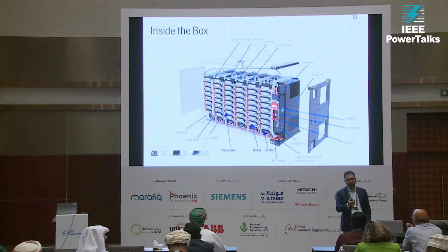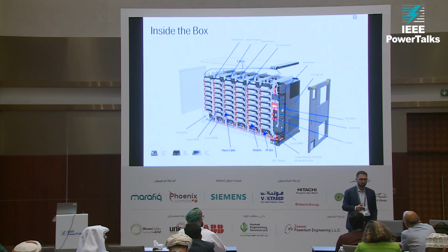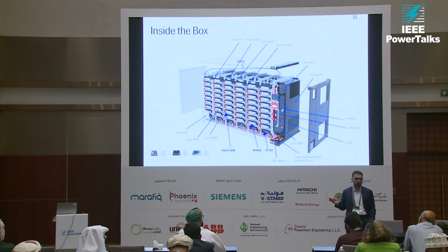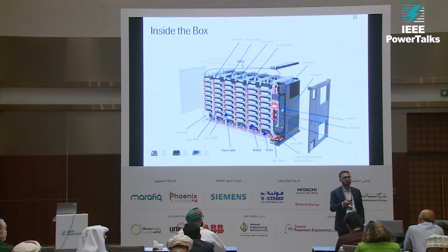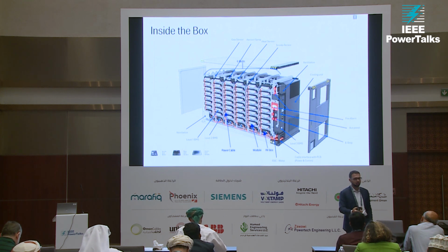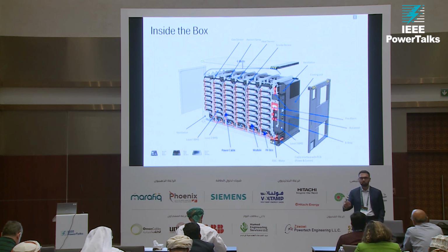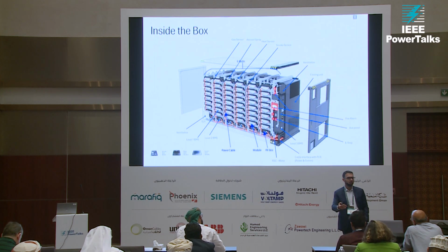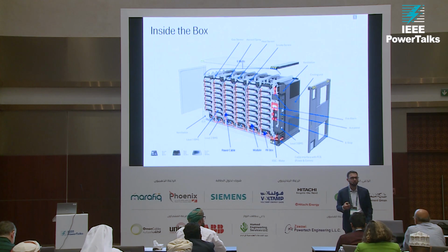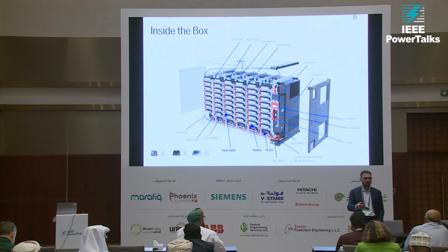Yeah, so that's a good question. That's a classification question, not really a device question. Just to speak on devices, we do have hydrogen sensors. So we do have measurements. The industry and the codes have improved to require a mitigation method that includes ventilation, for example. The original projects did not have that. So we did improve to actually include mitigation methods like ventilation. There are other methods like sparking, as they call it. So you burn the gas before it becomes too large a volume that could actually cause a fire. So you're actually having small fires that are not going to impact the system.